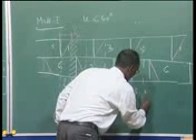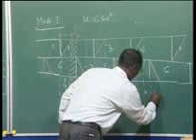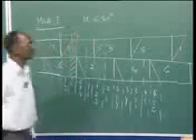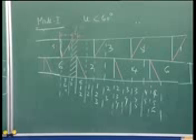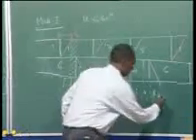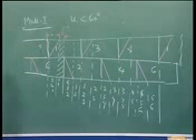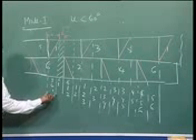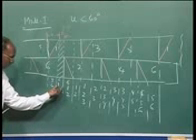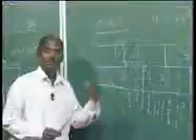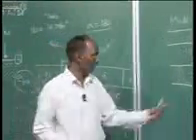We are getting here 4 5 6, and so on. So again we are getting the cyclic pattern, here 5 6 will remain, and then we come here again. So this is the case of the 2-3 valve conduction, meaning for the U period 3 valves are conducting, and for the remaining period, that is 60 minus U, 2 valves are conducting.